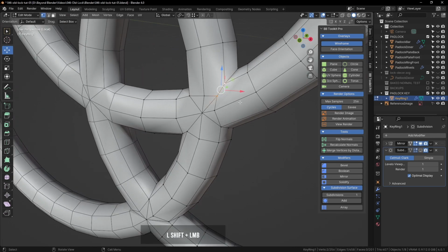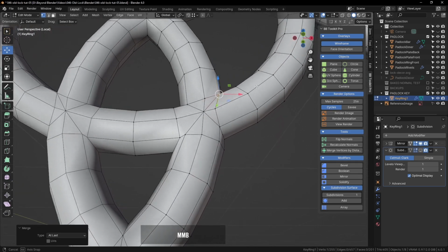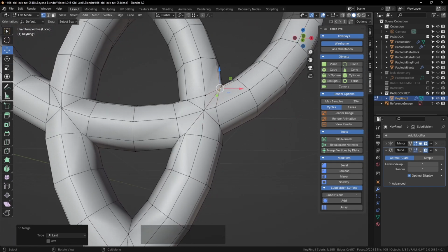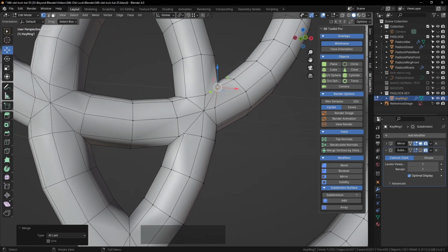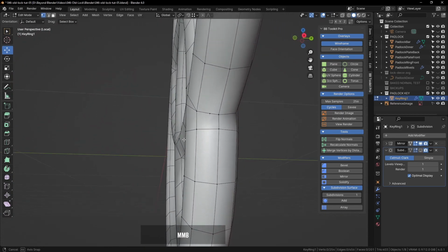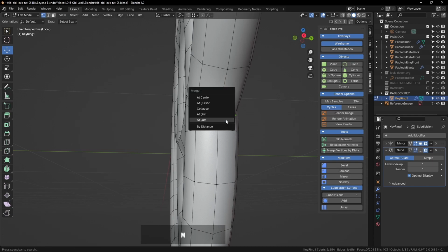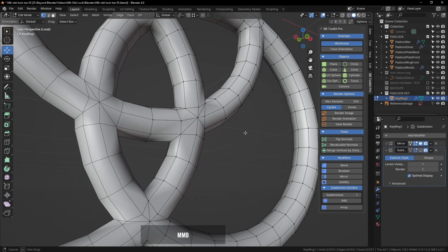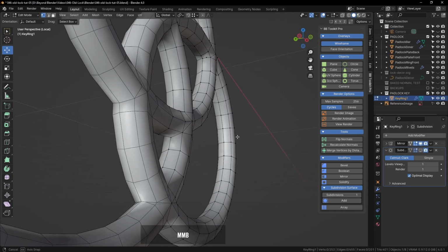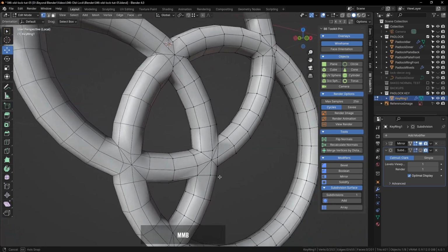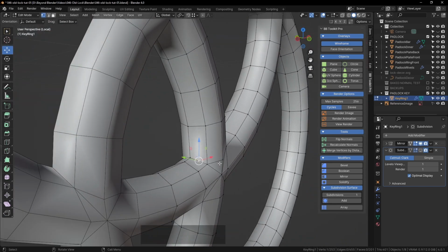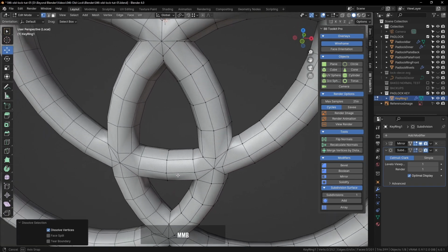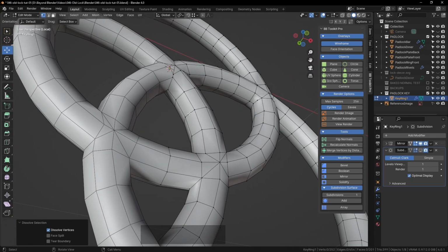It's very easy to miss stuff actually. I've always spotted the odd vertex here and there that I didn't spot as I was going through these. You can see just under there in that recessed corner, there's a vertex right in the middle, just sitting there. That one there, we go. So you can just merge that as well, or dissolve it. Make sure you do take your time at this stage, and make sure you tidy up as best you can. And that one there, I just pressed Ctrl Delete to dissolve that.